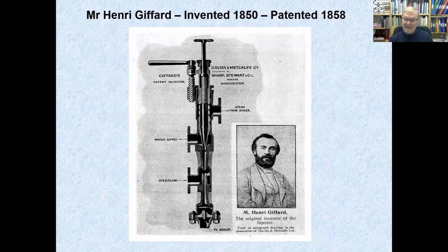Monsieur Henri Giffard. He was a French military engineer who was tasked with making a hot air balloon, and he wanted it powered. Well, the only power you had in those days was really steam. Well, to have pumps on board a dirigible balloon weighing a lot of kilograms to him just wasn't on. So he was experimenting with nozzles, and he came up with the injector. This isn't his original patent one. It's one that Davis and Metcalfe made, and it was supplied by Sharp Stewart.